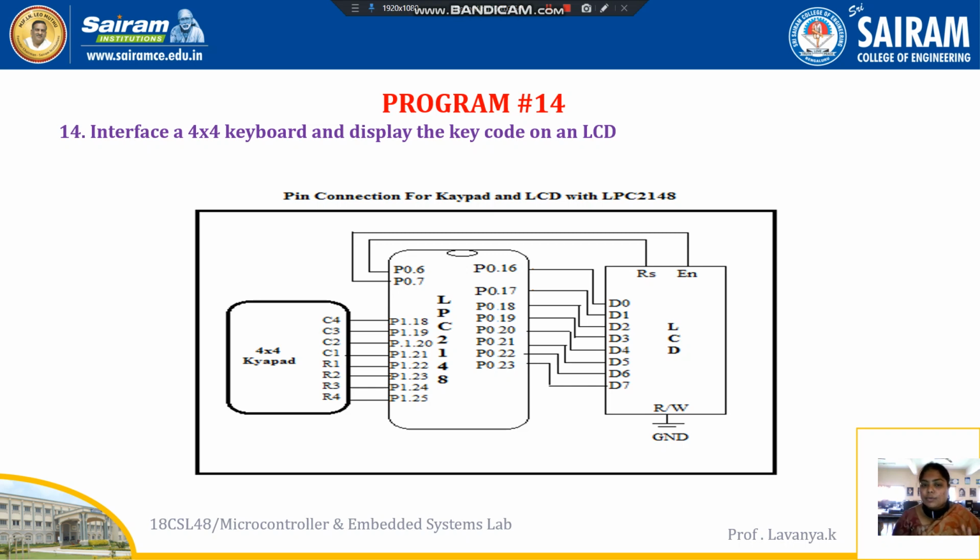These 4 I am going to consider as the input pins. The second set, the output pins, are again on port number 1, pins 21, 22, 23, 24 and 25. Now you got it, which are the output pins and which port we use for the transactions. So these are the fundamental connections between the LCD and the LPC 2148 ARM controller board. Now we are going to move on to the program.